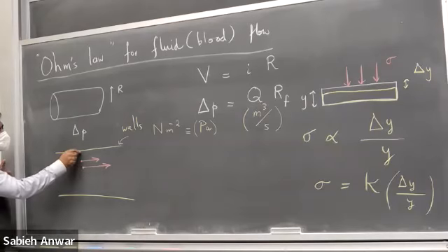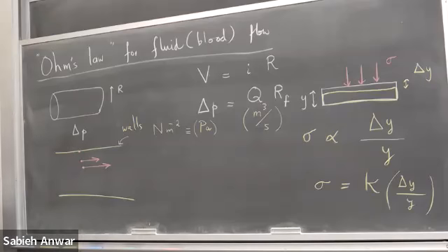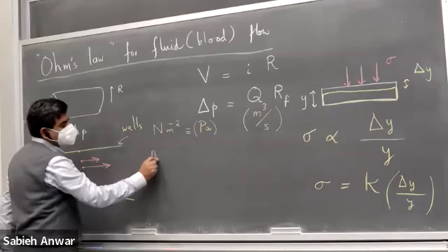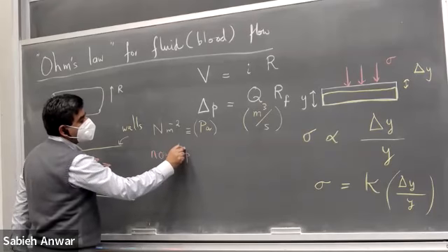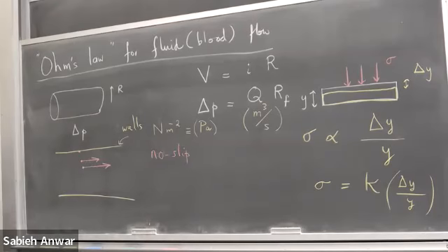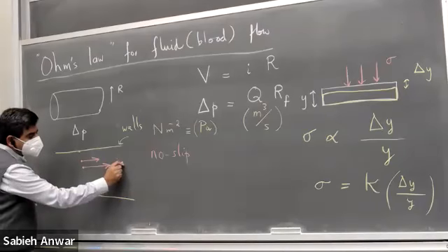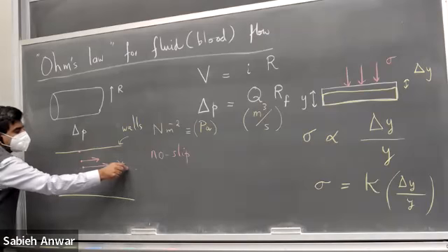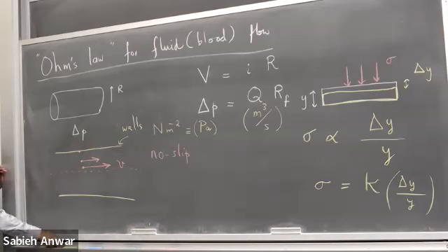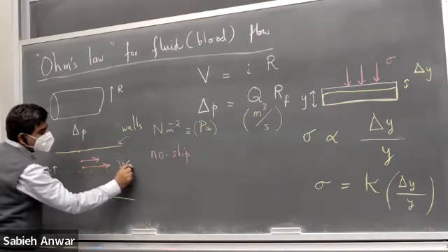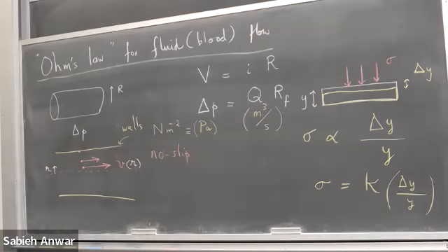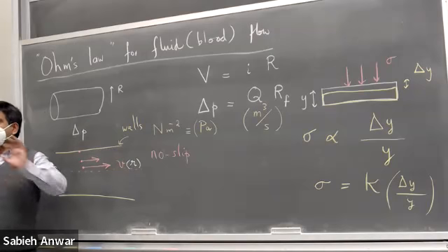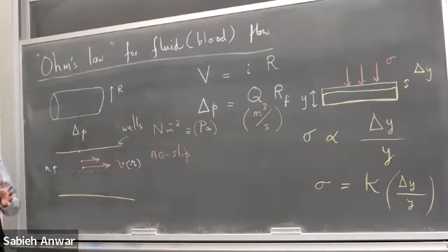It's also possible that at the walls of the pipe, the object is static. This is called the no slip condition. So we're putting in some assumptions in place. There is a distribution of the velocities along this pipe. Now, if I look at the axis of this pipe and define a parameter, which is the distance from the axis of the pipe, then this velocity is going to be a function of r. So the particles are now moving with different velocities. And this is what happens in a real Newtonian fluid.